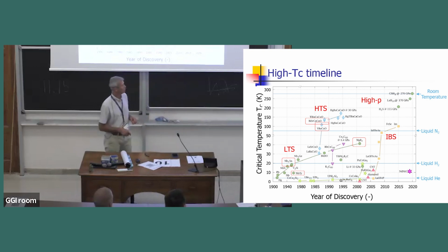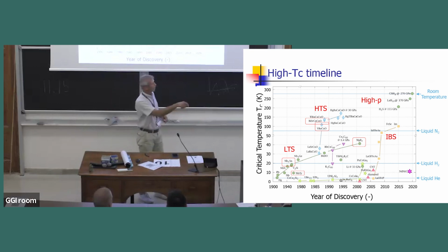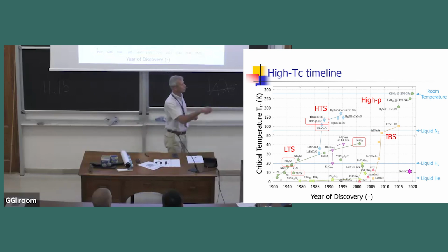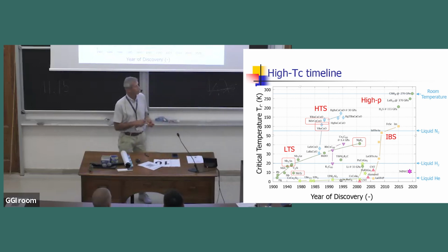They're technical superconductors. HTS, high temperature superconductors, now you understand why, are above liquid nitrogen, above 77K. In particular, YBCO, yttrium barium copper oxide, and BSCCO, bismuth, strontium, calcium, copper oxide. These two here. There are more materials, in particular one that was discovered in 2001, magnesium diboride. People were puzzled because that material is actually a strange low temperature superconductor. It's dual band. There are various modes in the crystal that make it possible to couple at a temperature of about 40K, above the 30K of BCS.